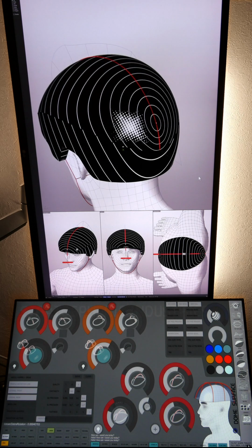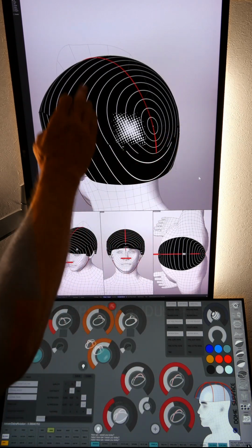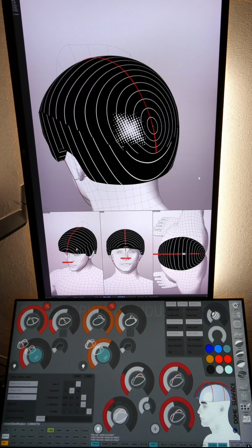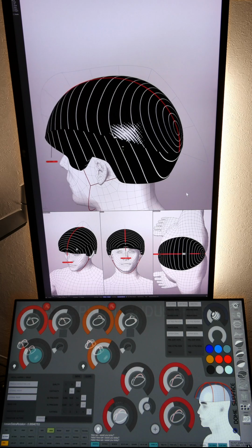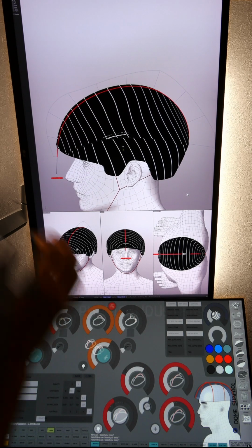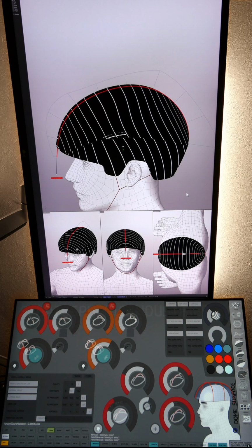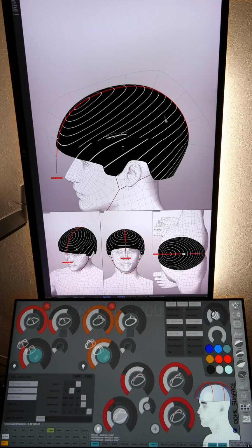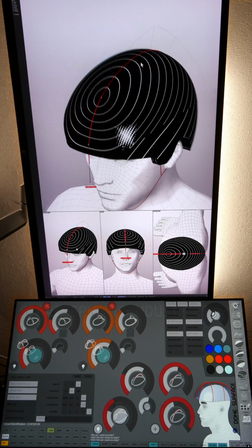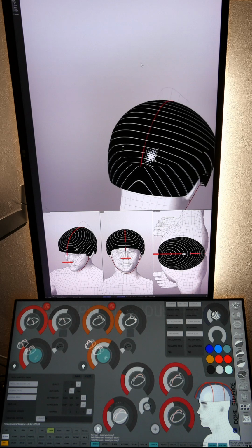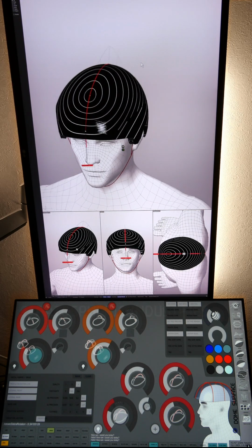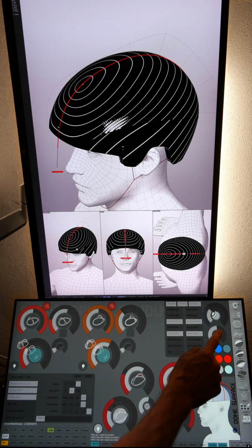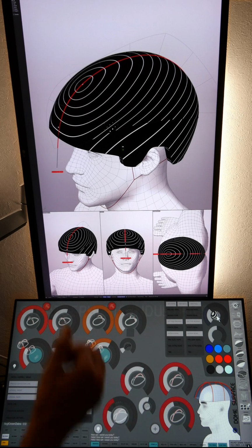Also, this design is not aiming towards tangency at the moment, but you can also check on tangency of a curve in general, on how the lines are lining up. Belt line curvature is not controlled for tangency at the moment, but it is fully capable of doing that. Rotating this down to the front spins that around so you can take a look at it from the front and analyze the different aspects of the curve. It's a very literal way of looking at the curvature. We'll bump the meshes down a little bit back towards the middle, and we'll turn off the isophote display.